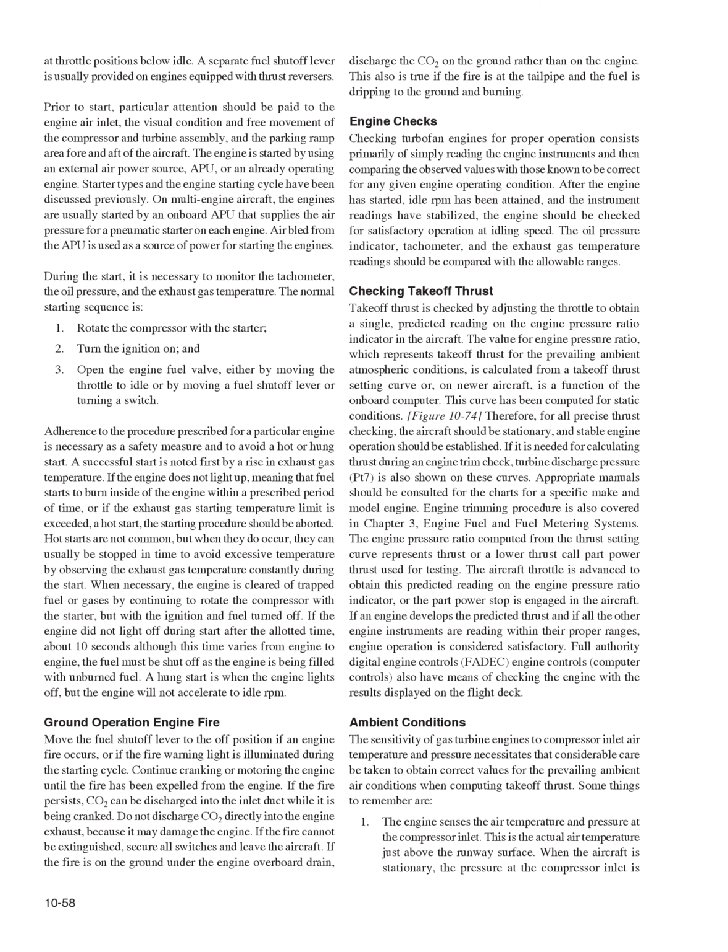If the fire persists, CO2 can be discharged into the inlet duct while it is being cranked. Do not discharge CO2 directly into the engine exhaust, because it may damage the engine. If the fire cannot be extinguished, secure all switches and leave the aircraft.